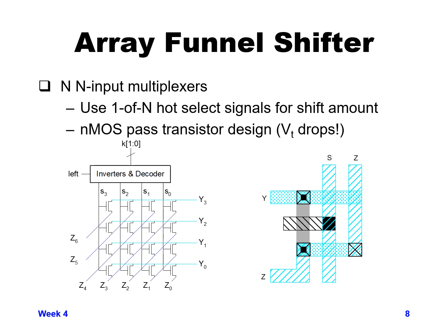And so you will get some VT drops in this particular case, and you would want to make sure to have an inverter or a buffer at the output of y3 through 0 in order to get a full rail swing after going through this multiplexer.